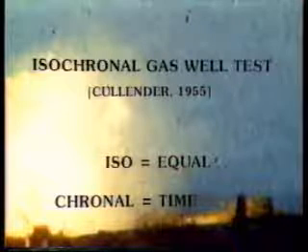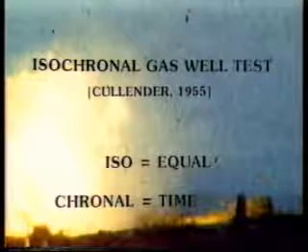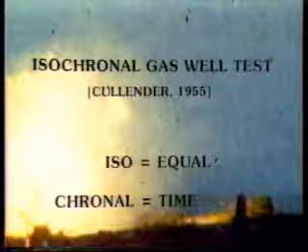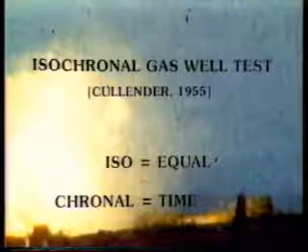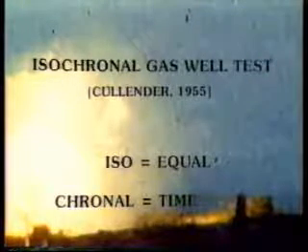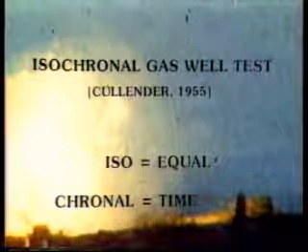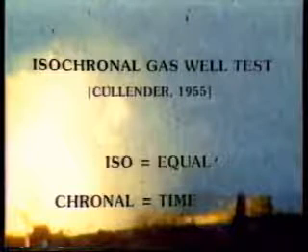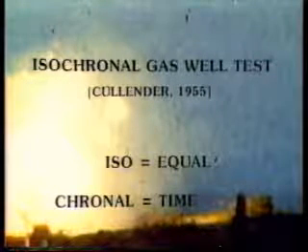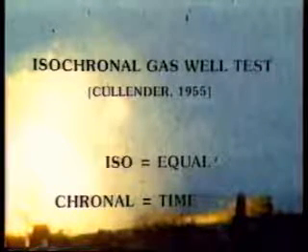The procedure followed in this test requires a series of flow and shut-in periods without the requirement that stabilization of pressure during each flow period take place. The pressure, however, must build up to its static value after each flow period. Details of the isochronal test are given in the course manual.